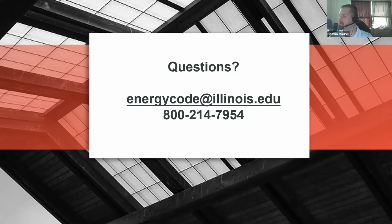Well, we did get a comment in the chat there. You need manual switches with the occupancy sensors, but they do not need to be inspected by the inspector. Yes, that is something that occupant sensors do require, a way to turn the lights off. Frequently, those are built into the switch itself, where there's a button on the occupant sensor, at least for wall-mounted ones. So yes, with occupant sensors, you do need a way to turn the lights off for most areas.